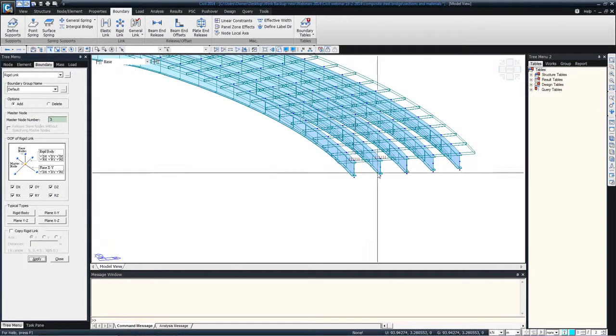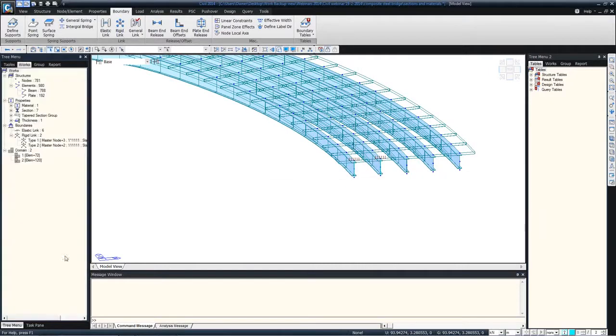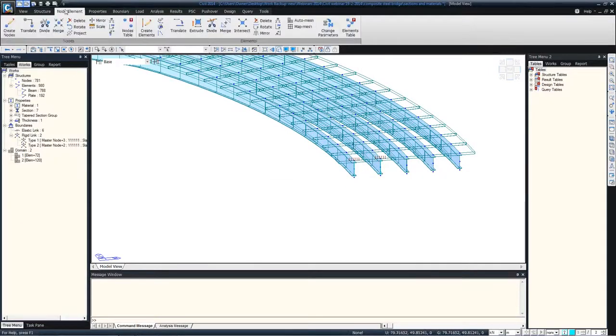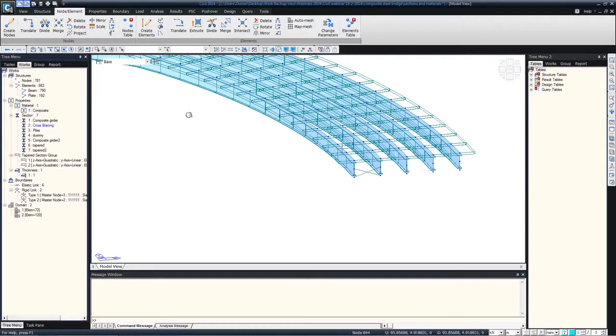Apply. And say I can then these nodes are now part of the same beam because of the rigid connection, and I can just simply model using any bracing section. You can just draw the bracing like this. So normally bracings will not intersect, so I'll check off the intersect option and just overlap them like this, so there's no intersecting nodes here. So that's how we model the bracings.